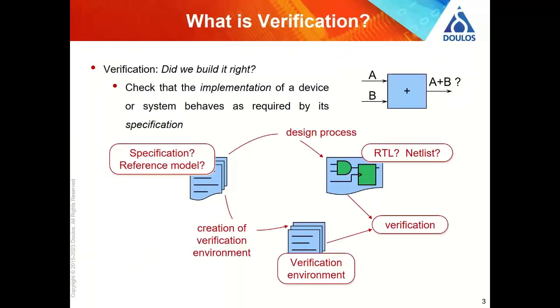So verification, what does it really mean? Well, it's all about finding out whether we've really built what was intended. Okay, so if we've got a device, is it going to behave as the specification said? Okay, we need that specification, and when we do the verification, we may have our particular version of the design. So it could be an RTL model that we're going to synthesize. It could be netlist. It could be something that's more abstract. Okay, but we want to check, does it meet the requirements of the specification?